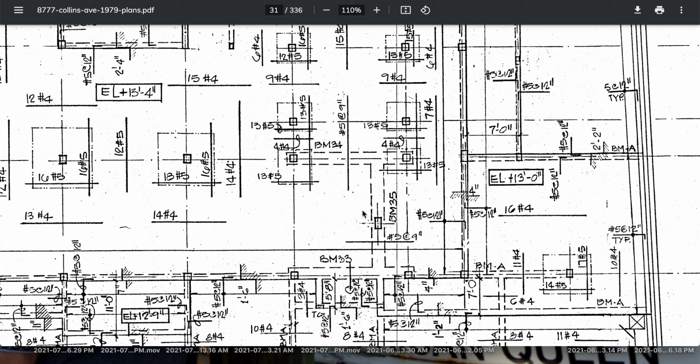And you can see this is sort of like what we have here. There's a deck and then a beam on top. You see the gap between there. So they built this deck, and then they put the next beam on top of it. Rebar usually sticks out of here, and when they pour around it, they can make this column integral into this one by locking the rebar, the reinforcement, into that deck below. That's a cantilever, and it's pretty beefed up to be able to take those loads. You see how it's cantilevered over, so the reactions are back here somewhere, and they share across this also, depending how this is built.